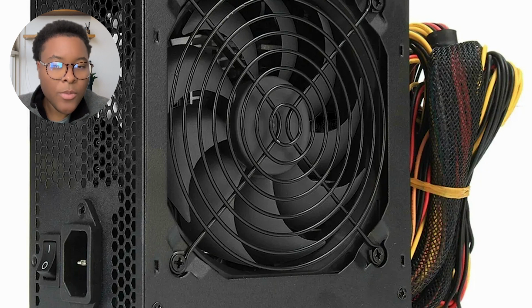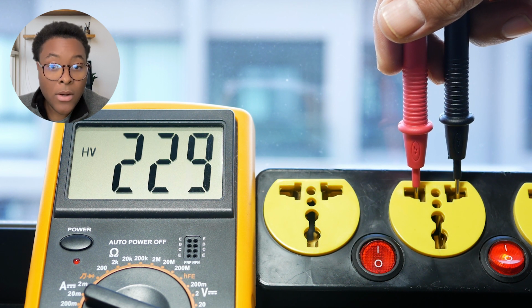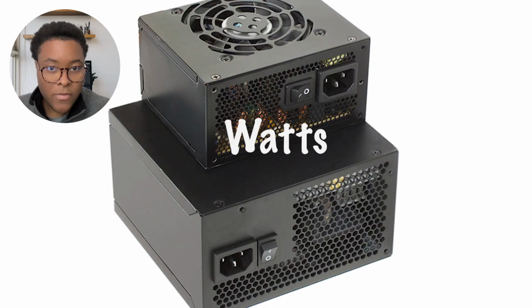And next up, let's go ahead and talk about power. So we're going to be talking about the power supply unit, the PSU. The PSU converts electrical power from an outlet into a form that the computer can understand. So what we're talking about here is AC to DC conversion. It supplies power to the motherboard, the CPU, the GPU, and other peripherals. The wattage of the PSU determines the maximum power the computer can consume, and it needs to provide stable power to ensure the proper functioning of components.